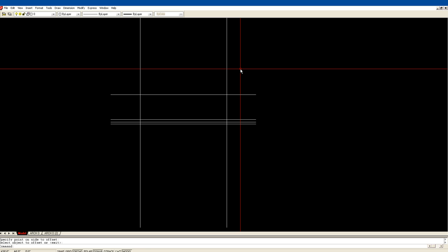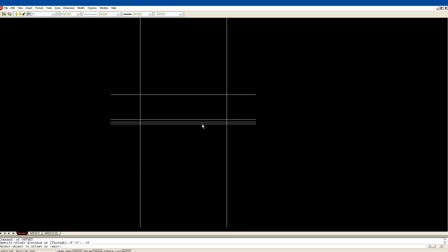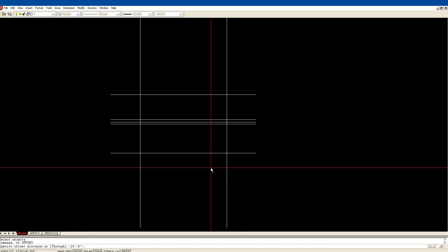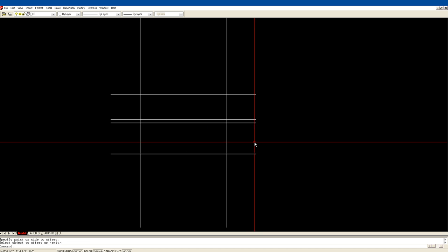Okay, so we've offset, that's the top of our main floor walls. Now we can go the other direction. We know where the top of concrete is, and we know that he wants a 10-foot high ceiling. So we can offset 10 feet. We'll pick this line right here, which, again, was our grade. This is our top of concrete, and so what we've just established will be the top of the concrete slab. So we can offset 4 inches. That'll be the thickness of our concrete slab.